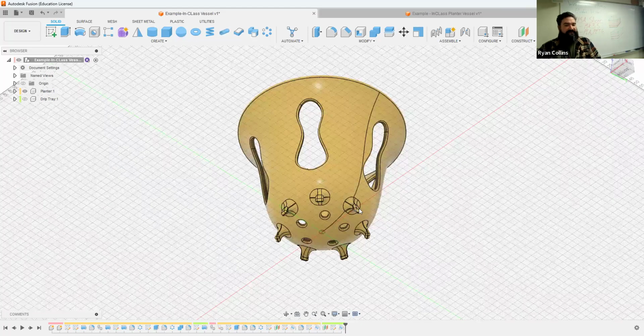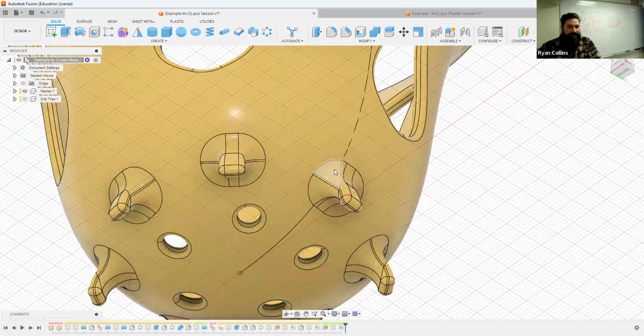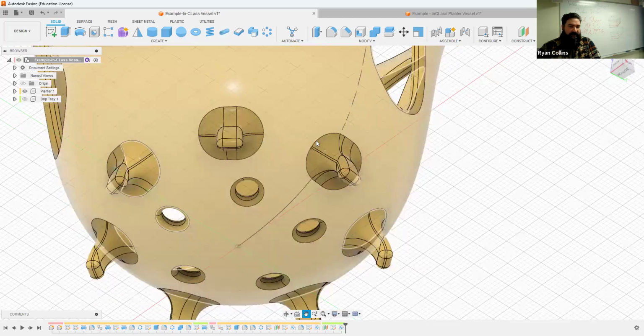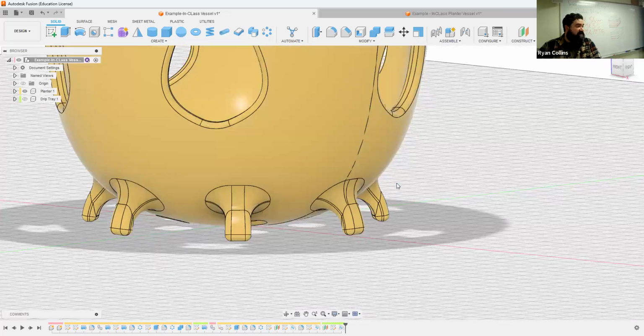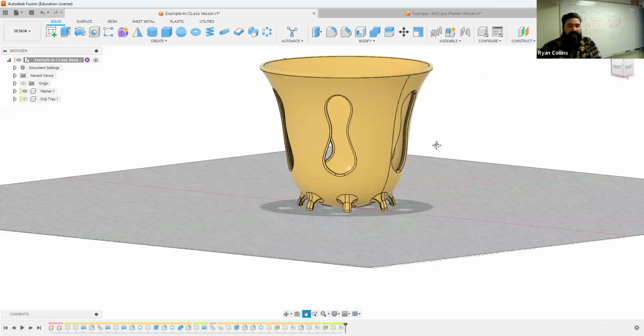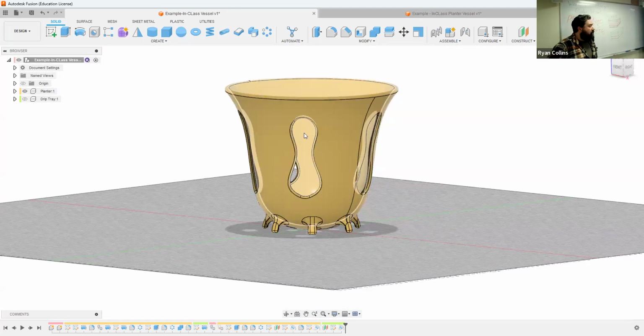partial revolve, so just by a little bit, to make one foot, and used fillet to make this blending feature, and then used the circle pattern tool to make a whole bunch of these same little feet. So you can make a cauldron, something like that. More power to you. If you're doing, like I said, the advanced feature or option would be making additional holes, that sort of thing. I grow orchids. I made more of a pot that has a lot more ventilation, so it'd be better for orchids. There you go. You can print them out that way.